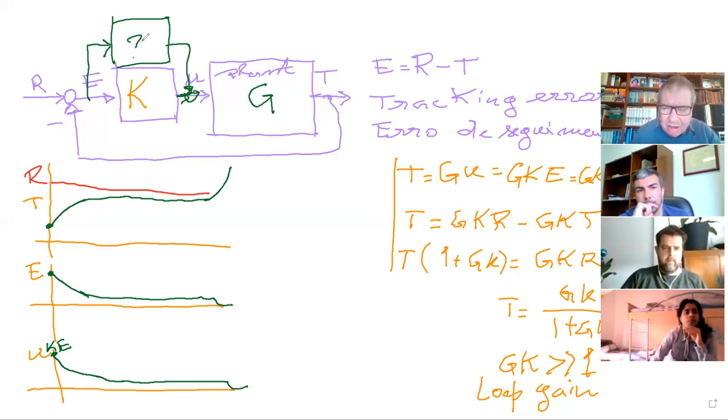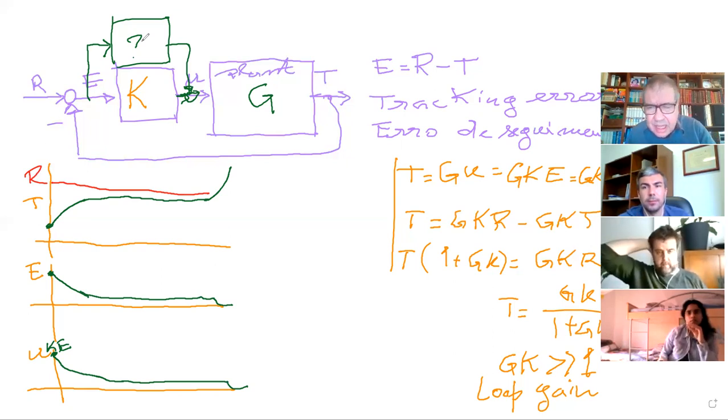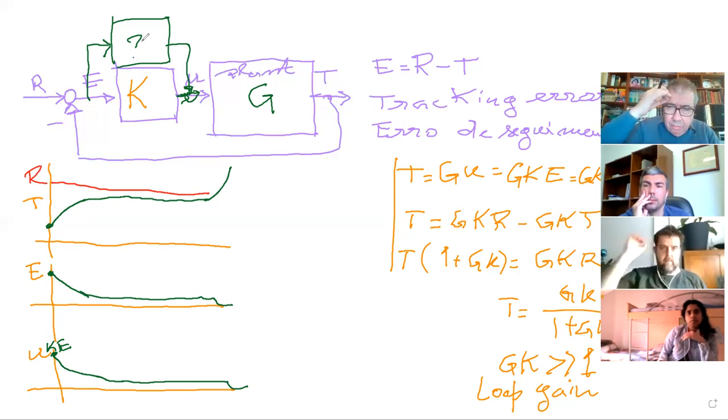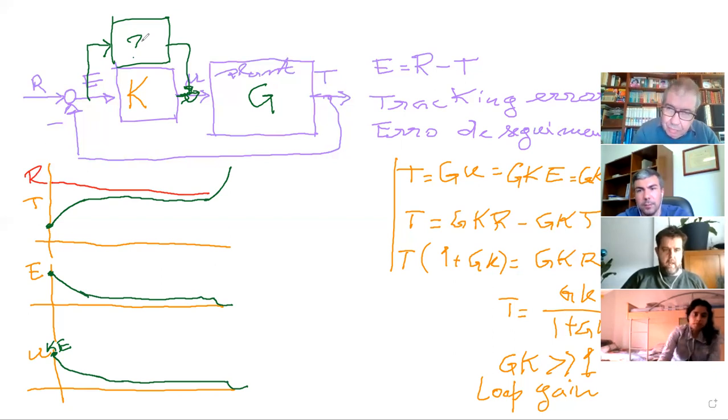So adding a constant is not a good choice. It would work if you could do all the precise computations of the energy and so on. You compute the precise value of the valve and you put it there. But then the night was colder than what you expected, and this constant would not work. So you have a disturbance.